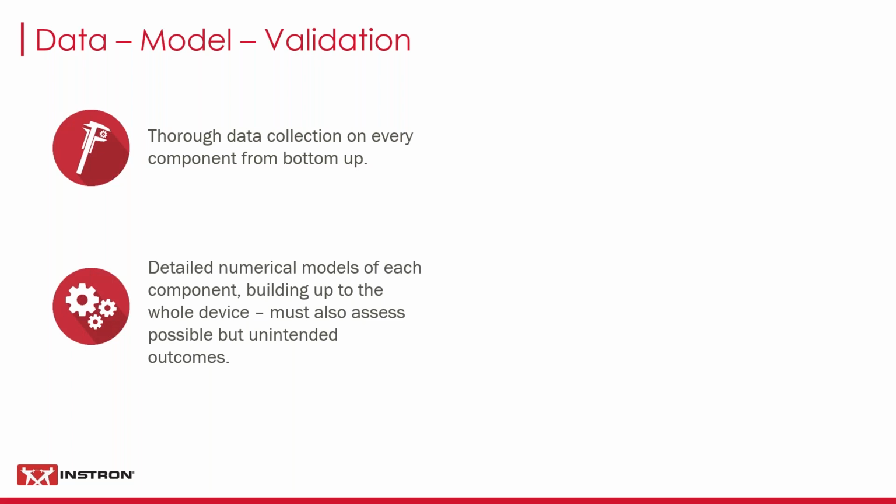Once you've got that data, or perhaps even before you collect the data, you should have in mind what your model is going to be and build. And you need to look at detailed numerical methods. So we're really looking at the finite element analysis world once you start getting into structures, and building up from component level. Make sure you have a model that describes your material properly and it matches with what your test says. And then you build maybe structural elements, and then you build up to the whole structure or substructure.